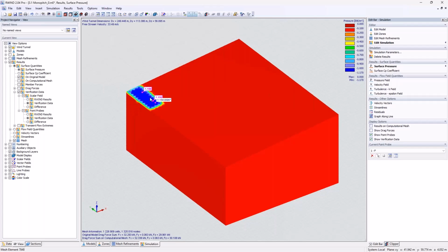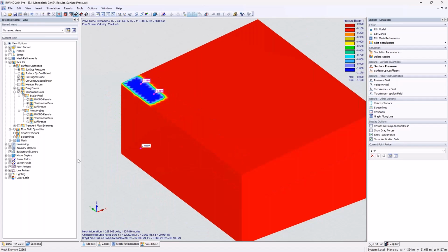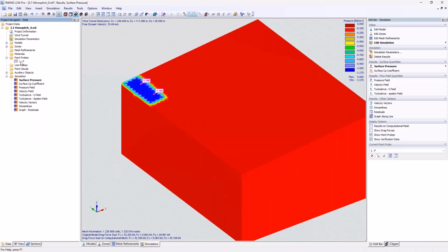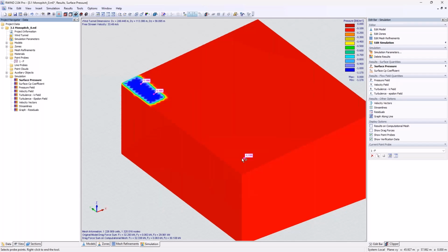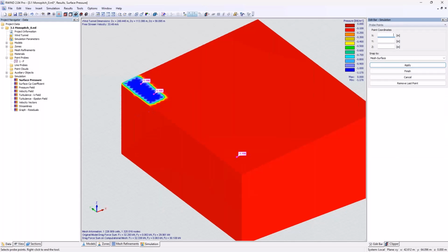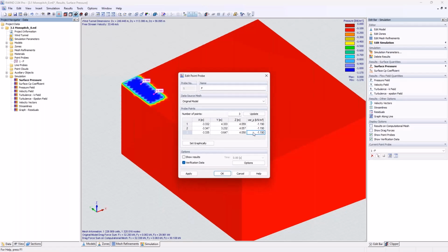We now inserted 2 probes for the zone. We restricted it to be only interpolated in this area. So what it tries now, of course, to do is to keep the minus 1.19, and to the boundaries, to the other surfaces, it tries to interpolate. We will now introduce some more points. So I will just enter 1 more in the other area, say okay. We go in there, it already has the latest value.